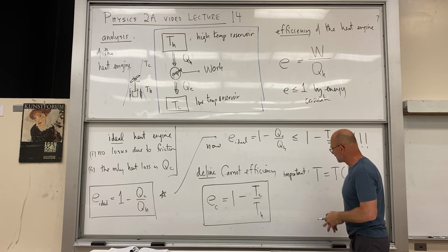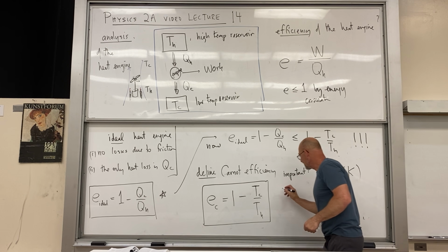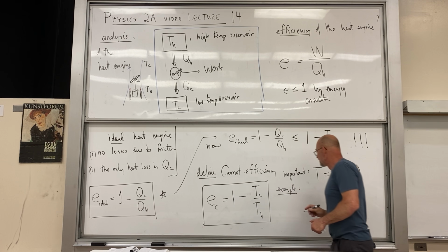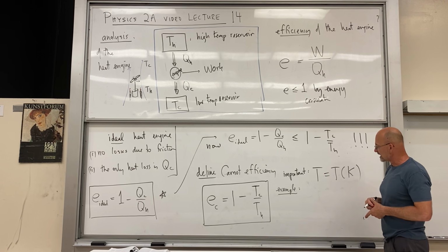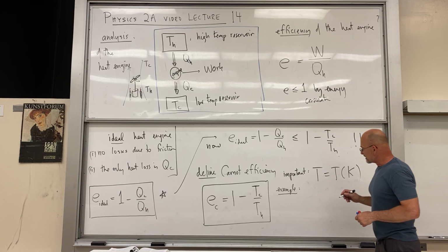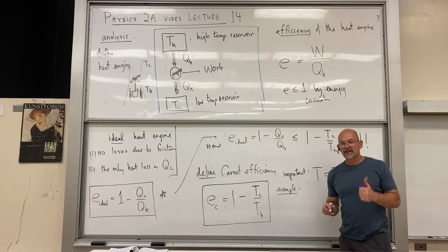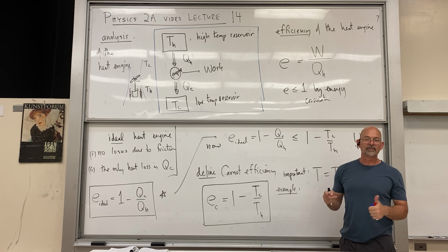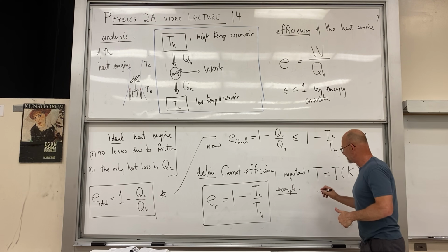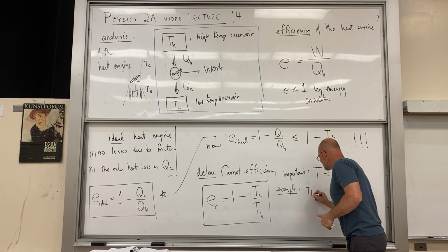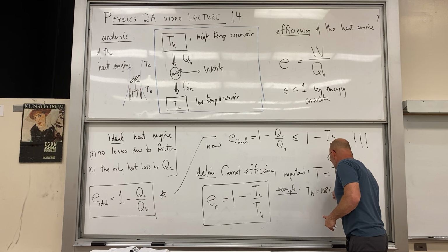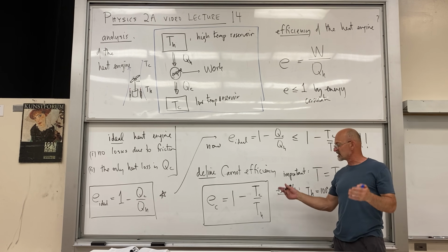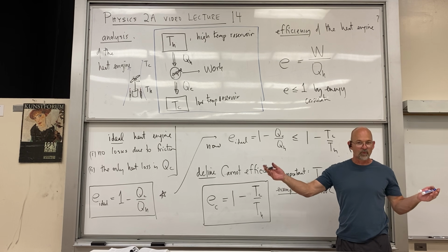Okay, so what about this Carnot efficiency? Example. All kinds of practical matters come into play here. First of all, we're going to imagine a steam engine that runs on boiling water, at no particularly high pressure. So TH is 100 degrees Celsius, and the exhaust goes to room temperature because our steam engine's working in this room.